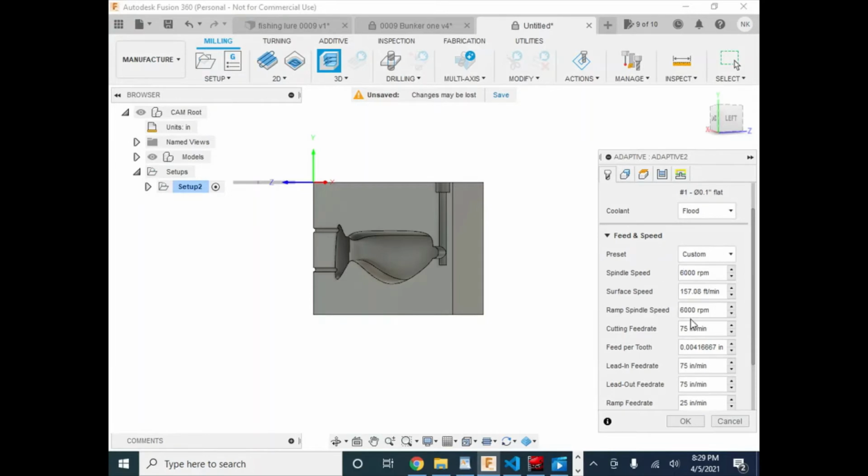Obviously, if your machine can't do 6,000 RPM, setting it here is not going to make your spindle go 6,000 RPM unless you have it set up to your computer. But again, that's more of a more advanced machine. This is where they're setting their RPMs from this menu, from the machine itself. Like when they run their G code, it'll automatically set their spindle to 6,000. If your spindle is like mine and not hooked up and it's manual, it won't matter.